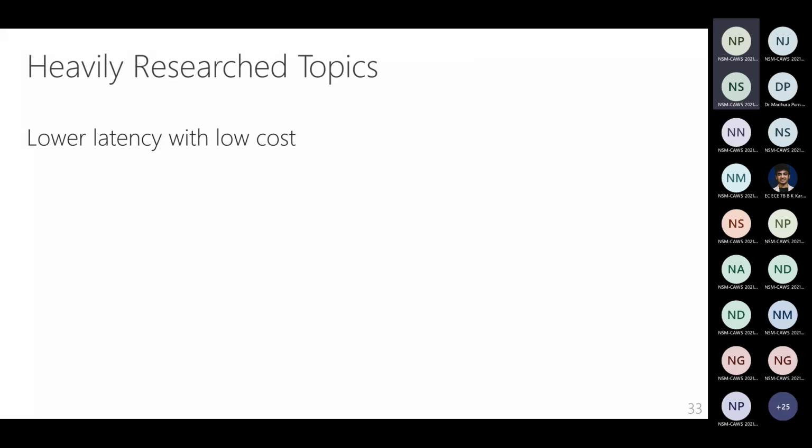As Professor Madhu mentioned, in the last 20 years, DRAM latency has actually not reduced that much at all. It probably reduced by 10% to 20%, right? One of the reasons is the fact that DRAM is a commodity, and all we care about from DRAM is that I want higher and higher capacity. So people have tried everything to ensure that we get more capacity in successive generations of DRAM, but they've not done much to actually lower latency. There have been some proposals around, but this is still a heavily researched problem.